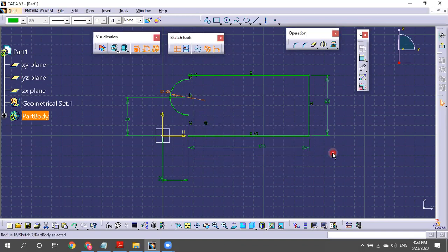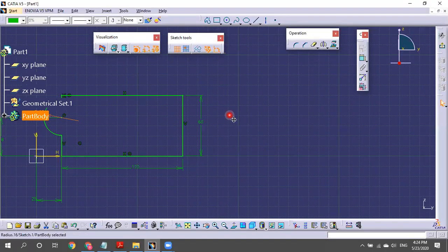So I just use this sketch format and ensure that I'm giving the sketch fully constraints. That is the meaning of creating fully constrained sketches. So the lesson learned for you, always remember to switch on these 4 things, these 5 components. And we learned what is meant by dimensional constraint, what is geometrical constraint. So I'll just go back now.